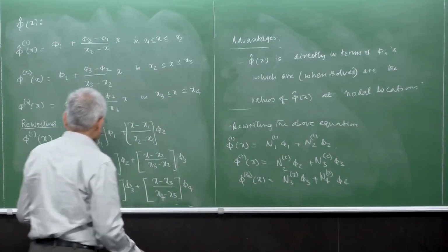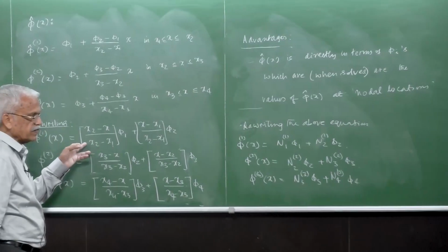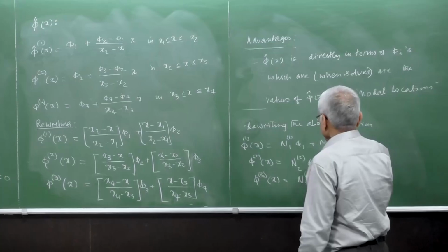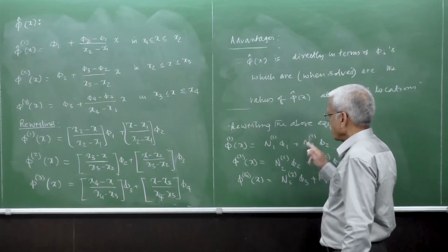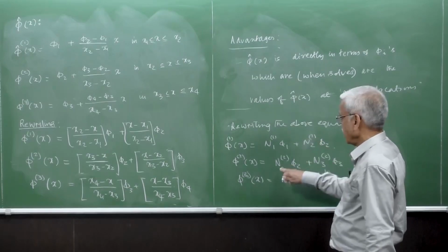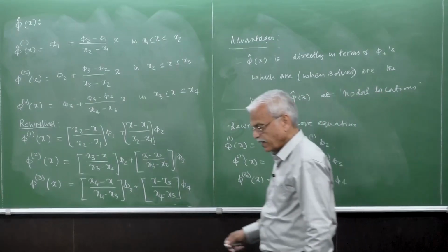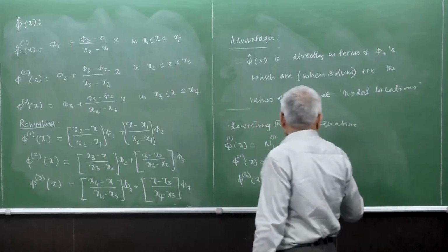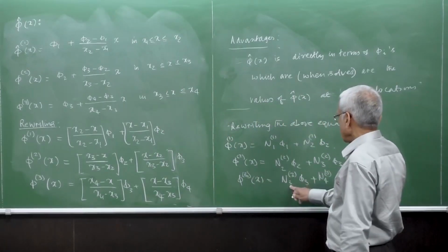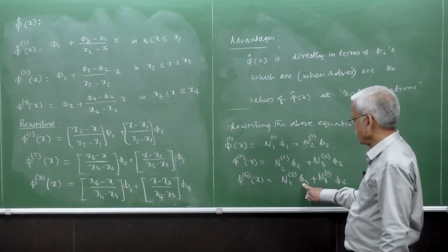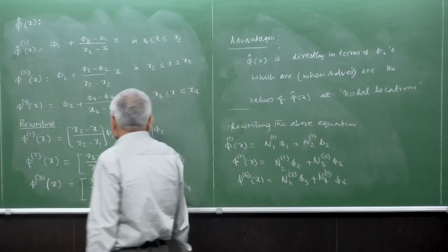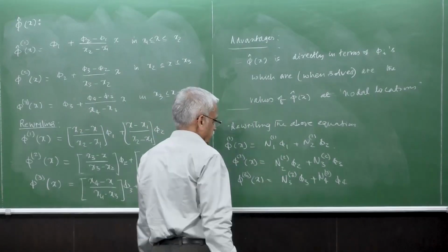Okay. So that means that these functions, we are renaming them as N1, and this also has superscripts 1, because this N2 here is repeating, right? So this is N2 of 1, N2 of 2. So they have different expressions. And so similarly N3 of 2 and N3 of 3. Because N3, we are putting it because it is the function corresponding to the coefficient phi 3.